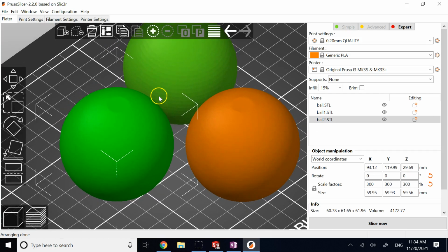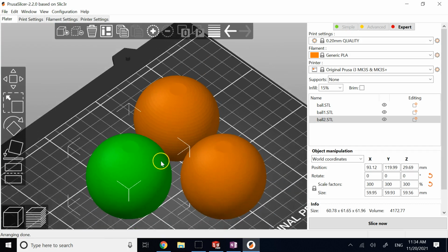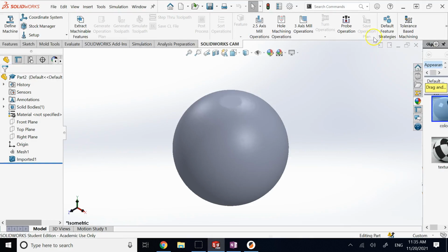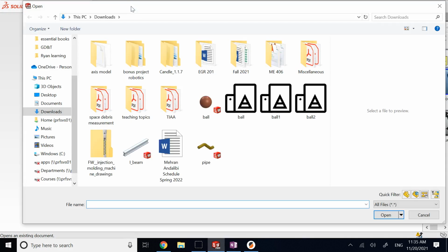And if I bring them closer, you can see that ball 2 is a lot closer to the original one than ball 1. You see this crater shape is not as smeared as it was in ball number 1, because I avoided simplification and smoothness and used the maximum details I could. So this is the idea of ScanTo3D, and again, I have to warn that if the surface of the STL file has sharp edges, then when you convert it into a surface or solid model, you're not going to get as clean and sharp an abrupt transition.